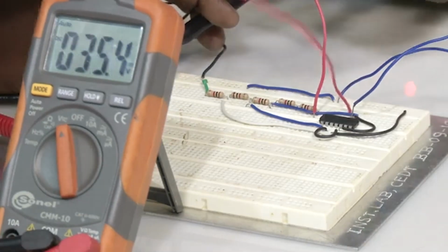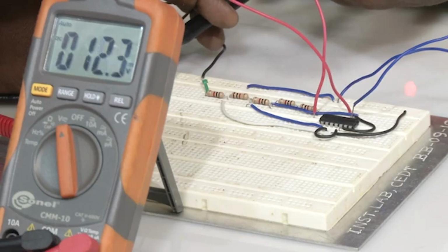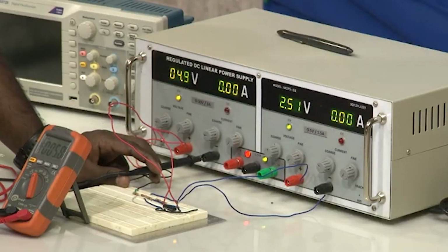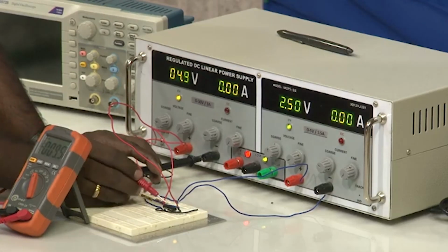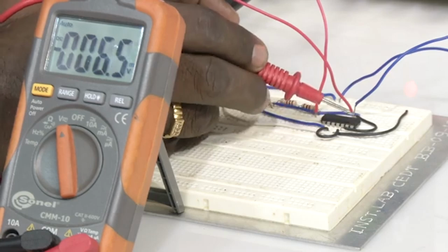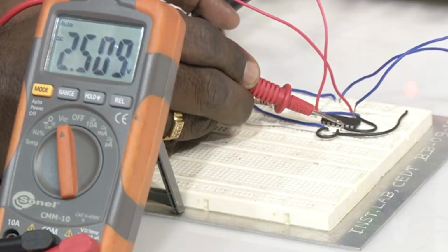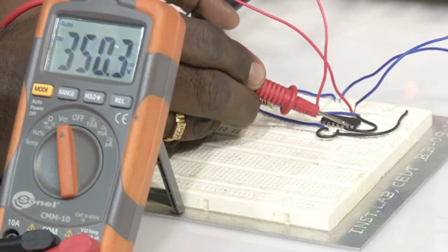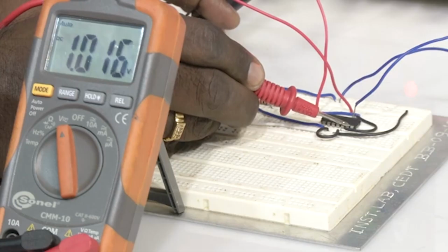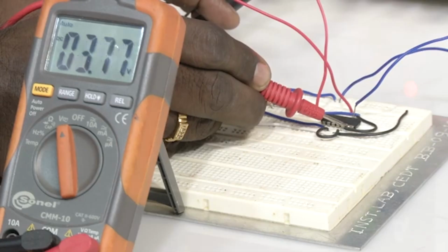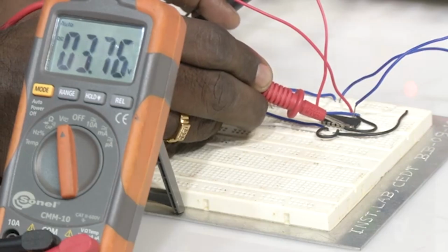Let me change the input voltage to 2.5. So, now the input voltage is 2.5, we can see that. Again we will observe. So, this is the op amp 1 part, this is the positive input terminal, which shows you 2.5. This is the negative input terminal, which is 1 because the reference value is 5 volts. Now, what about the output of C1? It should be 1, observe. So, 3.76 volts, which means 1.